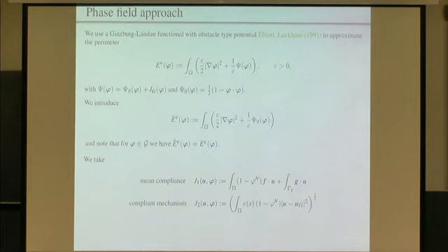We have a similar thing for our compliant mechanism, where we're trying to get as close as possible to our target u omega. Again, we've got our weighting function, and this is multiplied by 1 minus phi N. Again, we want this to hold where we have material and not where we have void. So here is our objective functional, alpha J1, beta J2, and then this regularization E hat. In our objective function, as we see, we're not taking into account this indicator function.